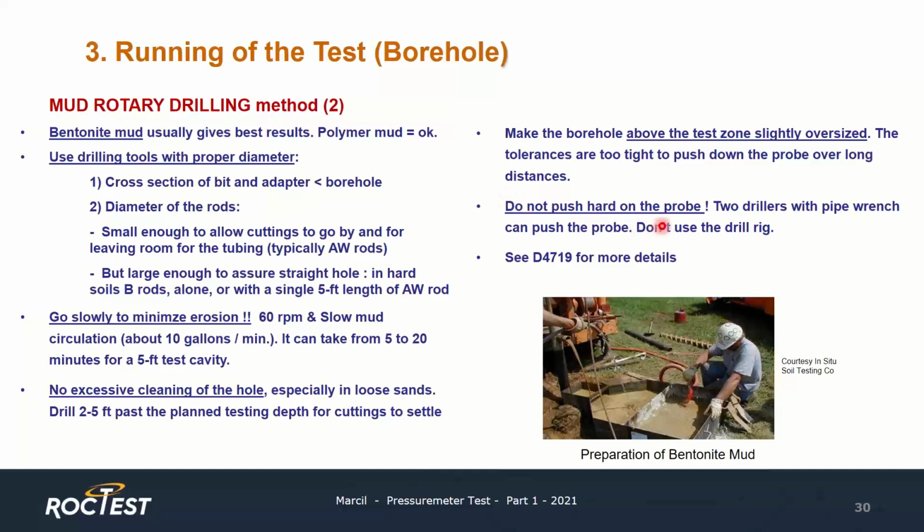And it is important not to push the probe. You should not use the drill rig for pushing the probe in place. Two drillers with a pipe wrench can push the probe, no more. So there's a learning curve for these drilling methods. It is good to work with a drilling crew that has some experience, or at least to plan at least a day for learning all this or making all these adjustments.